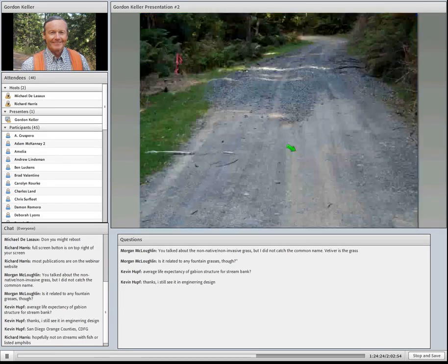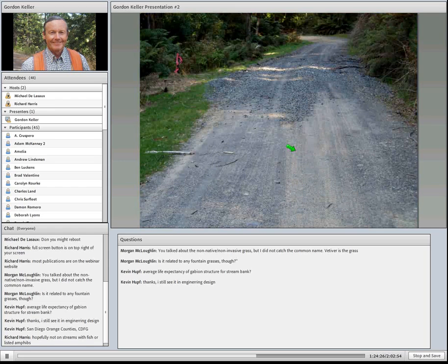And something we often do is just spot rocking. Now this is a real poor man's approach, but if you have a localized problem area, a soft area, we just put in a few cubic yards of rock, and then the rest of the road's okay. That's very appropriate for low standard roads. Like I say, we call it spot rocking. It's just going in as needed.